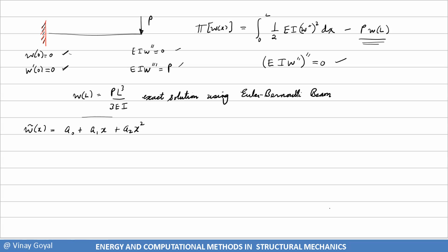And we found earlier, through the earlier example, that a good approximation to this problem is A naught W tilde A1 x over L squared. And I'll just do a two-term approximation. Why not? You will see that this one satisfies the essential boundary conditions accurately and correctly. You can see that yourself. Very clearly it satisfies these essential boundary conditions. So we're good to go.